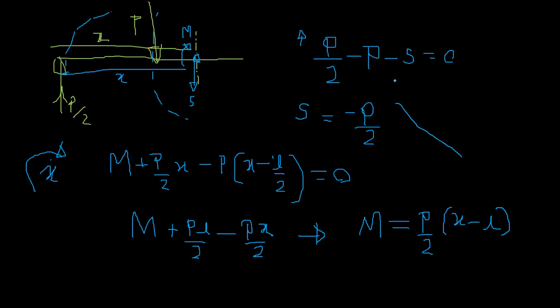So the first half of the bending moment diagram was okay, right? So the second part at L by 2, it is again PL over 4. It should be continuous, right? It should be a continuous bending moment diagram here for this case. And if X equals to L, it is 0, right? So this is your shear force diagram, which is entirely negative. So what does that mean? This is a sagging bending moment, right?